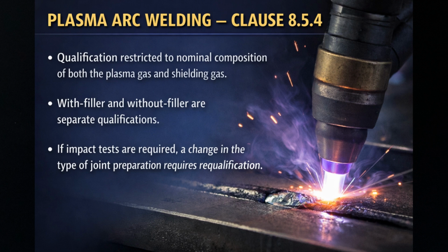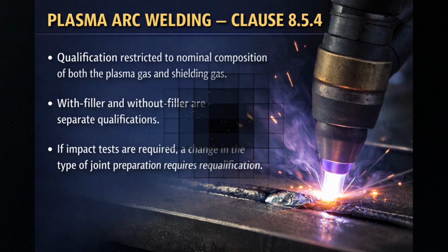Plasma arc welding, Clause 8.5.4. Qualification restricted to nominal composition of both the plasma gas and shielding gas. With filler and without filler are separate qualifications. If impact tests are required, a change in the type of joint preparation requires requalification.